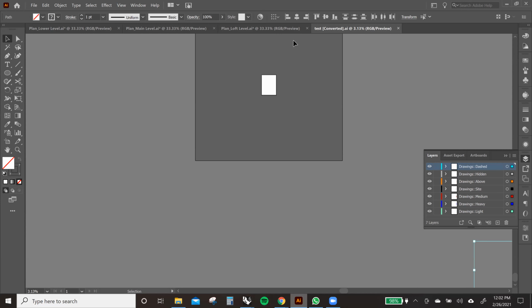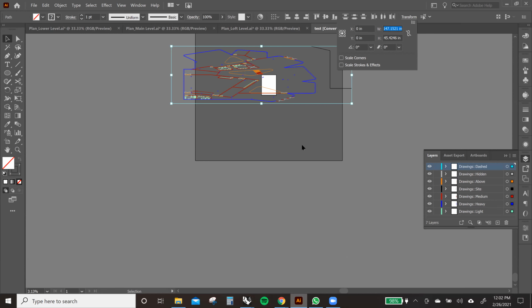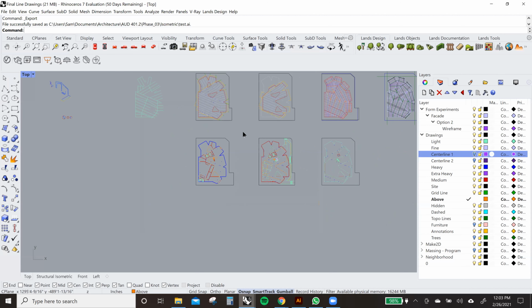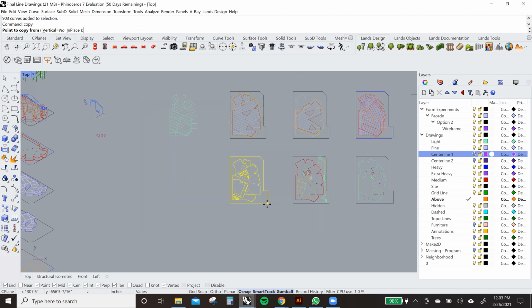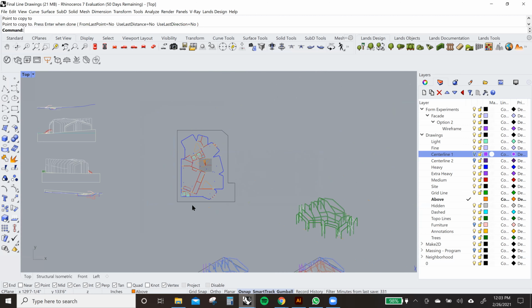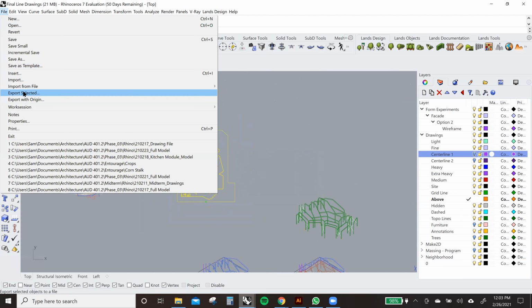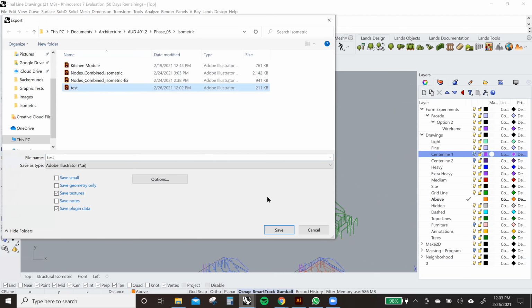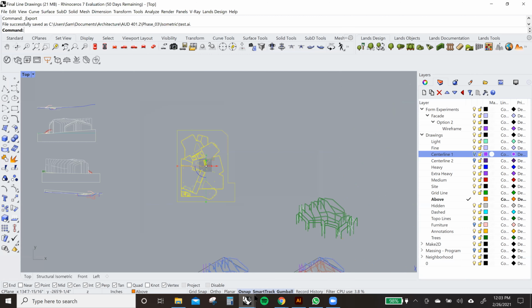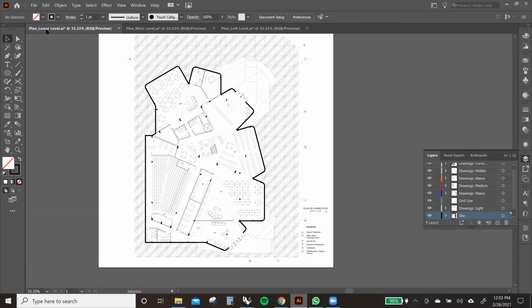It's off to 0. Yeah. So a thing worth noting is that wherever you put your drawing in Rhino compared to where the 0, 0, 0 point in Rhino is, is where it will be sent in Illustrator. So often I will move all my drawings to the 0, 0, 0 in Rhino, which I leave empty like always, so that I can export them correctly into Adobe Illustrator. It's just one of the quirks of going between these two softwares.